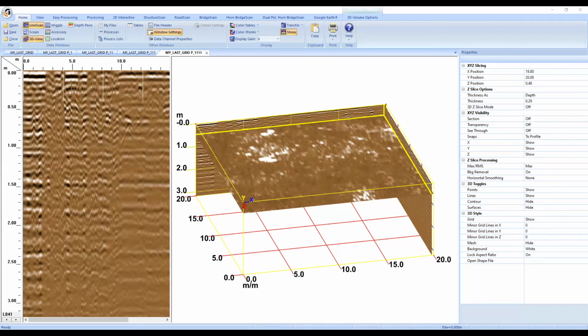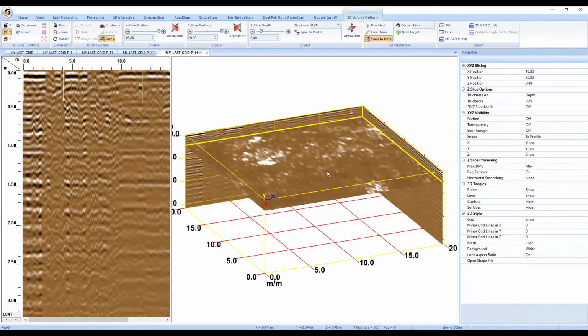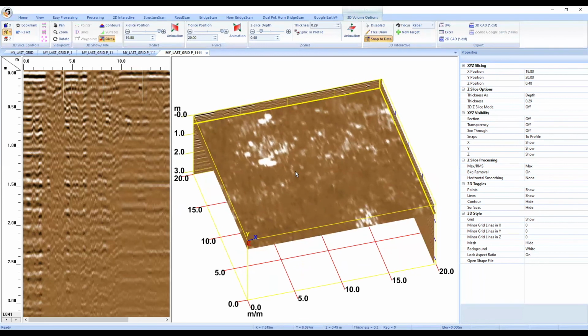All right. So to get to this last 3D view, there are definitely a few routes that you could take. I took a slightly different route than what I normally do by starting with time 0. You're going to have to start with time 0. And then after that, I did a deconvolution and then a background removal to finally get it ready for its view. You can also do IIR background removal, some range gain.